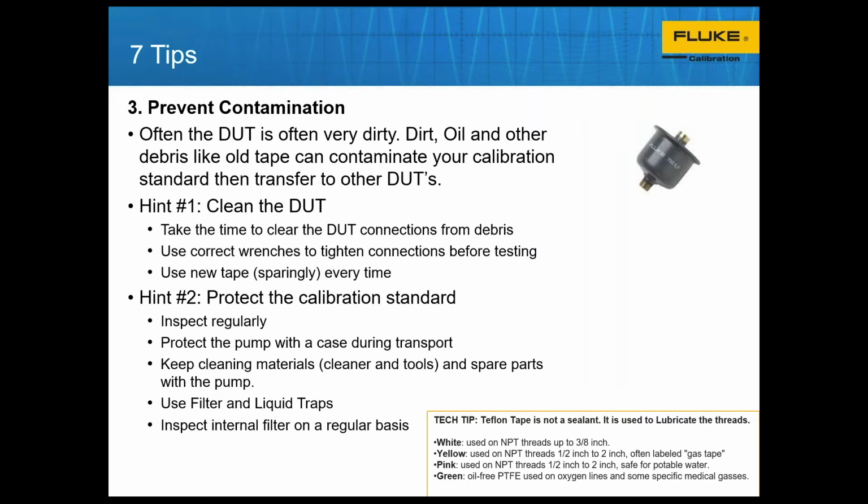Protect the calibration standard. So inspect it regularly. Protect your pump with a case during transportation. You've spent a bunch of money on a good pump. Take good care of it. Keep your cleaning materials that you would use to clean your device under test or clean the pump itself. And spare pumps, keep them with the pump.